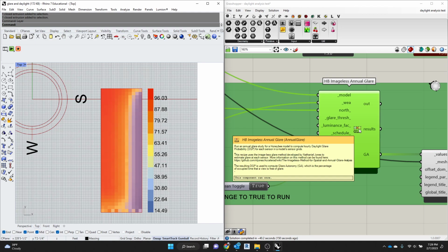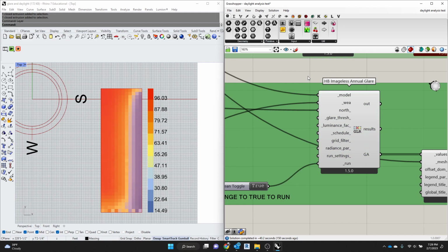If you're running these and you see orange in Grasshopper, that means there's some error, something being plugged in is just not being calculated properly. If you see red, that means there's a critical error, it's unrunnable, and little red or orange bubbles will pop up. If you hover over that, it'll tell you what the actual error is. Zach, I don't think, had the latest and greatest. There's an EXE file. Yeah, Windows. Okay. Cool.